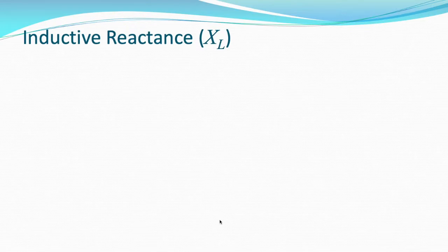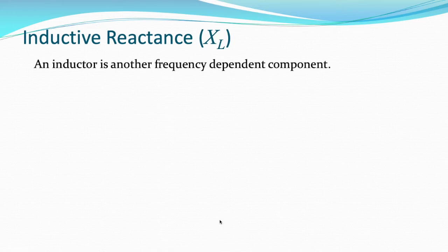Okay, hi folks, this is the second part of our inductors lessons, and we're really talking about inductors in AC circuits. And just like capacitors that have capacitive reactance or resistance to AC signals, inductors also have reactance. They are active components, and their reactance, or resistance if you like, is dependent on the frequency of the AC signal. So the inductor is another frequency dependent component.